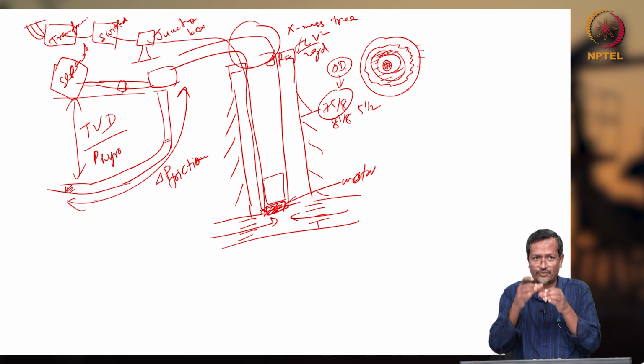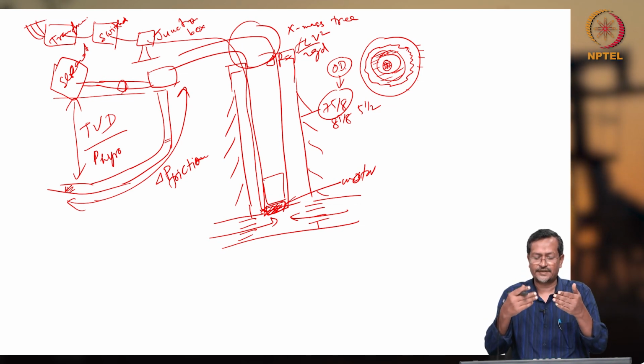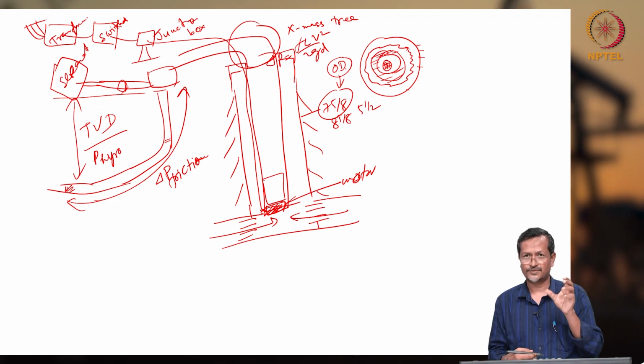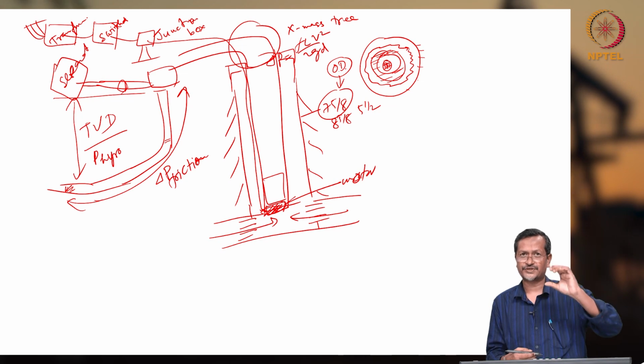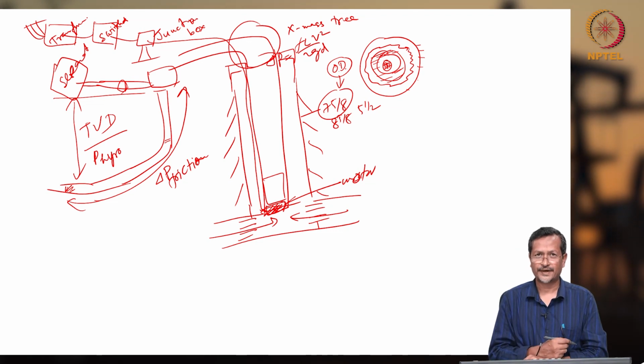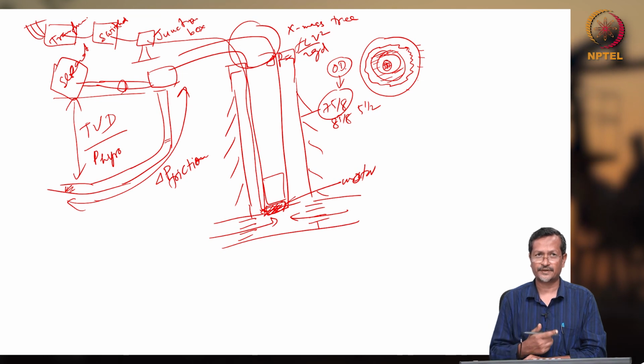So the flowing pressure you got. Now if that pressure is sufficient, then it is okay. If it is not sufficient, then you have to give some inducer. That inducer, or small axial pump, will give extra pressure to the main centrifugal pump or main ESP, and then the ESP will develop all the fluid. Now you are creating two-phase flow, or you have free gas. Because of lower NPSH, gas will come out from your fluid, and that will create a problem.